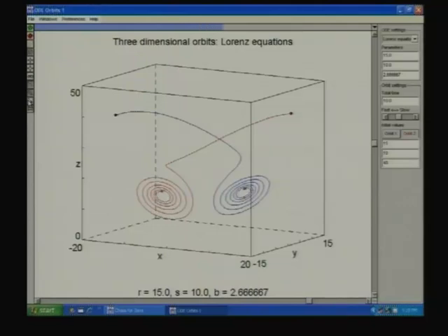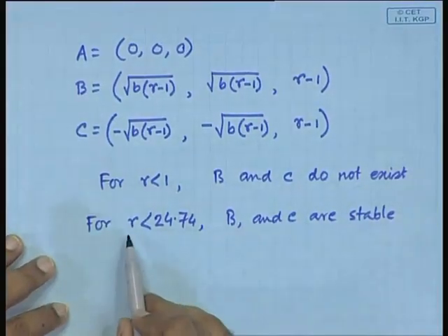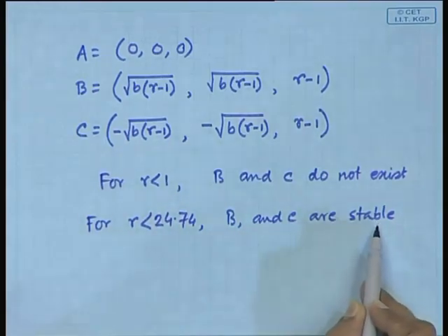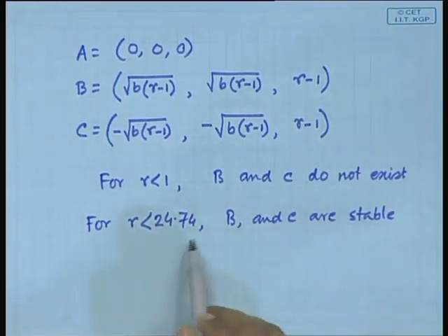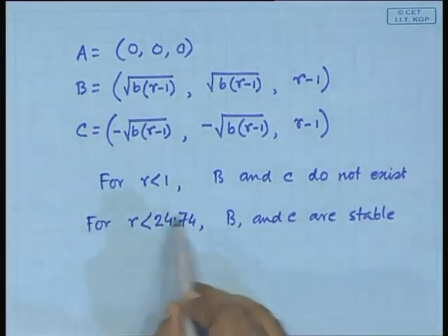That is one of the properties of a linear system. Now, tell me what will happen if I now progressively increase the R. If I progressively increase the R, then you will see that so long as R is less than this, they are stable, which means the real part is negative, and then it goes through real part 0 into the positive side at this value.